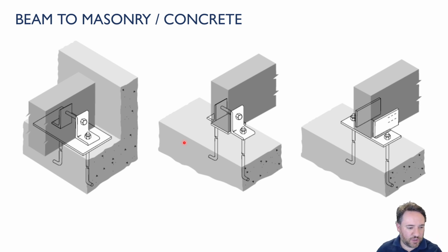And so if I have wood directly in contact with masonry or concrete, then moisture can easily wick through from the concrete, from the masonry directly into the wood. And that might provide an interface where it is often or always wet or moist, which means that I could end up with my wood connections basically rotting away.